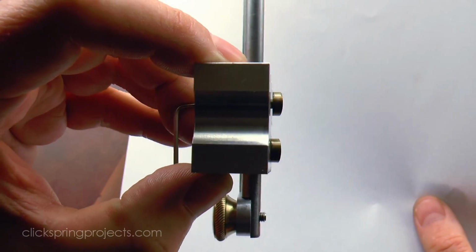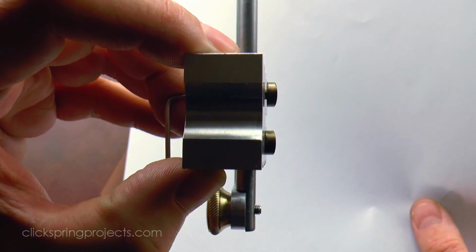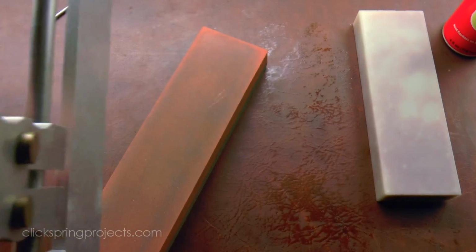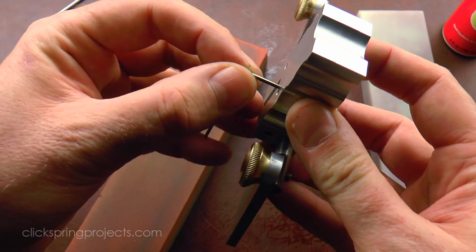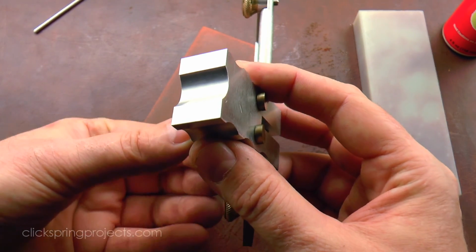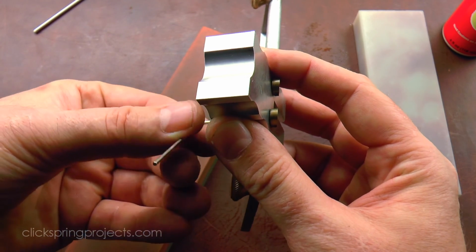With equal adjustments to the jack screws, each button can be advanced until both are sitting just barely forward of the plate. Whatever it takes to move one button forward, then the other can be adjusted in exactly the same way, by applying the same number of turns to the screw.